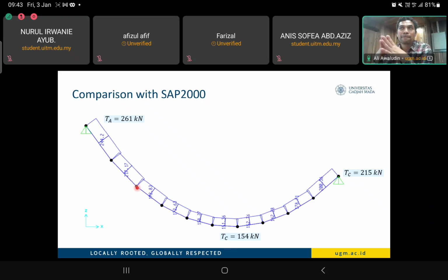That's why it is very efficient, because in many cases the best mechanical property of our material is the tension one. When you compare with wood, the tension strength is much higher compared with the compression strength. When you compare with steel, under tension it can reach the yield strength, but under compression it can easily buckle. Also in a beam member, you have bending moment, which initiates cracks, with tension in the lower side and compression in the upper side. That is less efficient compared with uniform tension forces. So the cable is a very efficient structural system.